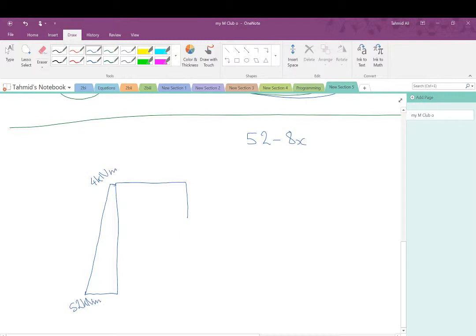Now, at this corner, the bending moment must continue. It will never be something like this. 4 kilonewton meters here, if it occurs outwardly, then this will occur. This will also be 4 kilonewton meters. It needs to continue; there can't be any discontinuities. So if you had it the other way around, and you had something like this, then it would also be inwards.